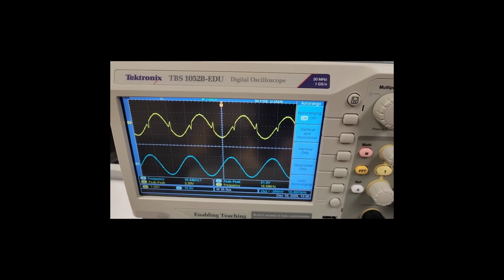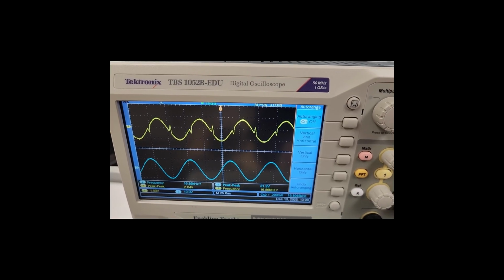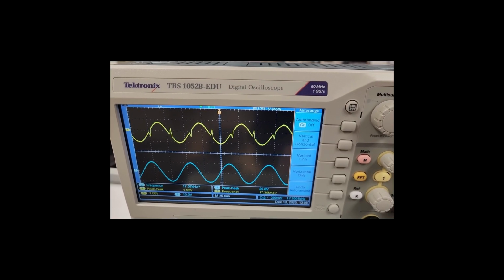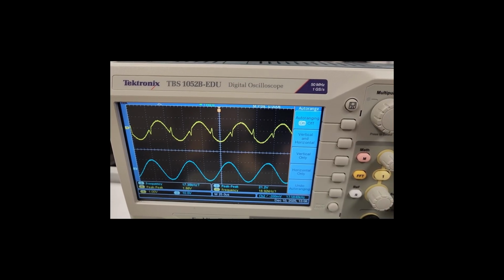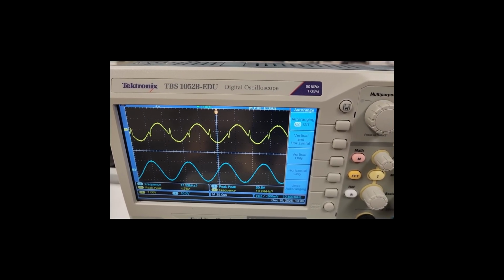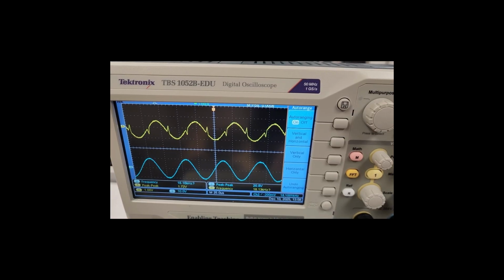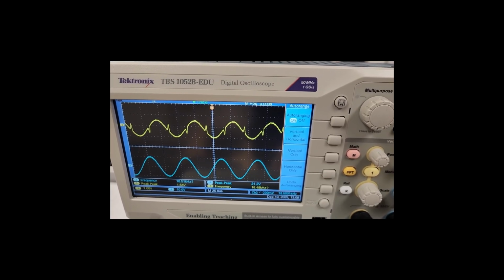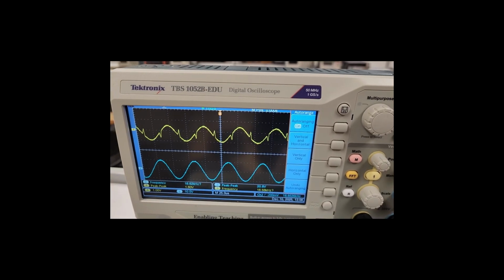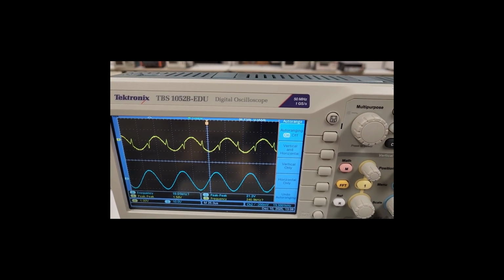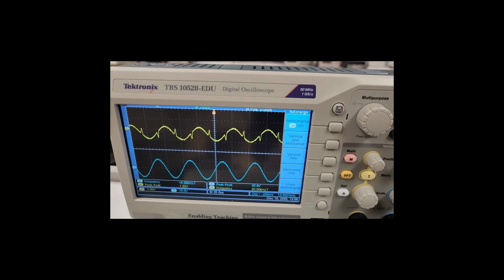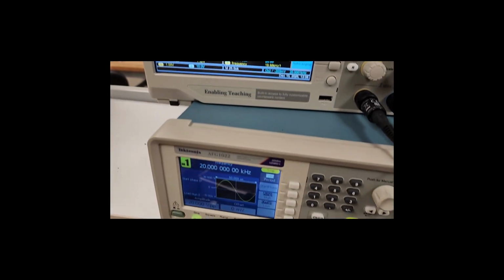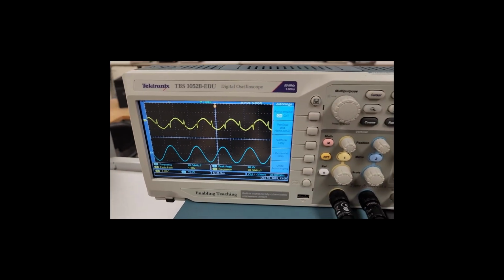If we keep going up, I guess I could take it a little bit further to show you those spikes. You see those spikes are going to keep getting larger and larger, even though our gain is diminishing. We do have those slew rate limitations, and you can see them right here in the oscilloscope, all the way up to our 20 kilohertz, and you can see that definitely exists.